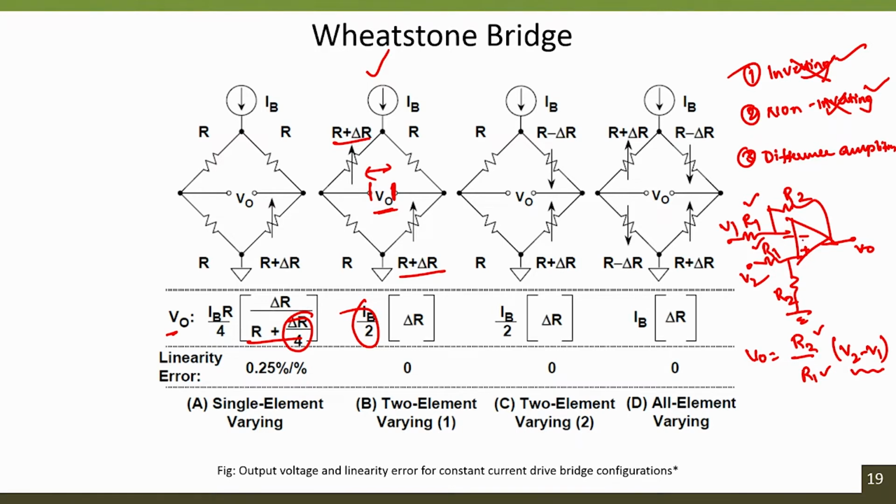this case, since the output from the previous stage is not directly connected to the input terminals of an operational amplifier, the chances of having a loading in this case are higher because of the input resistance value. Selection of input resistance is also very much important.